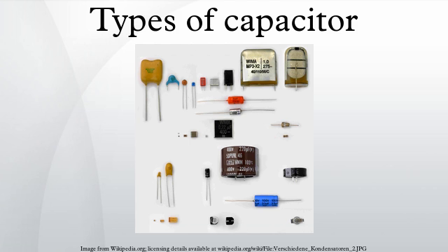The losses result from two physical conditions: line losses, including internal supply line resistances, the contact resistance of the electrode contact, and line resistance of the electrodes, and in wet aluminum electrolytic capacitors and especially supercapacitors, the limited conductivity of liquid electrolytes; and dielectric losses from dielectric polarization. The largest share of these losses in larger capacitors is usually the frequency-dependent ohmic dielectric losses. For smaller components, especially wet electrolytic capacitors, the conductivity of liquid electrolytes may exceed dielectric losses.